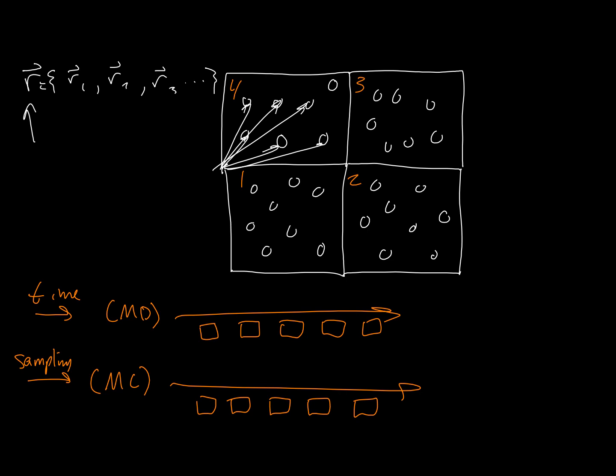When it comes to more amorphous or complex systems, we don't have a good way to characterize the fluid structure of water versus benzene versus toluene. With a crystal structure, you say it's FCC or HCP with this structure and this symmetry. They've got a whole classification system. So crystallographers in material science will go straight from the crystallographic pattern to its symmetry, because there's a finite number of crystal structures that have been discovered. When it comes to more amorphous and complex systems, like fluids and soft systems, we typically go from the diffraction pattern to the radial distribution function because there's no good classification system for that.